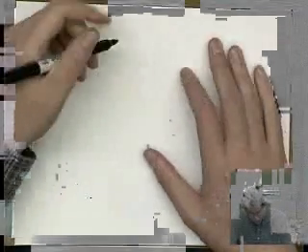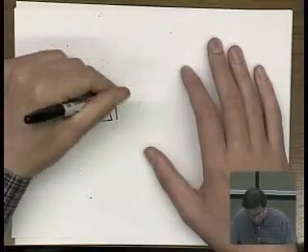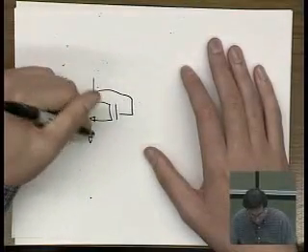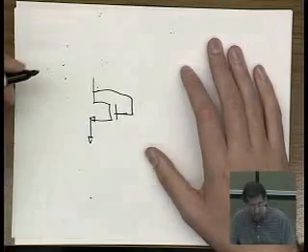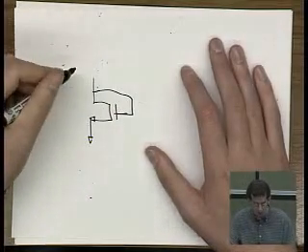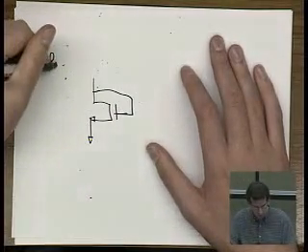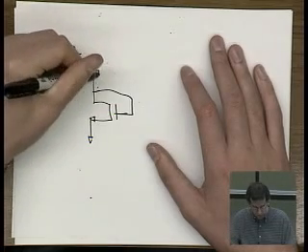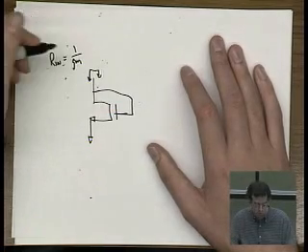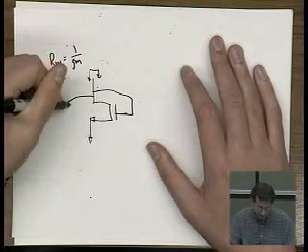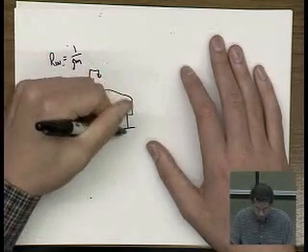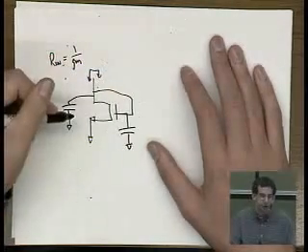I mean, because what you're saying is, okay, so this device, at DC, Rin equals 1 over GM, right? So now we're going to say, well, there's all these extra capacitors hanging off. Okay?